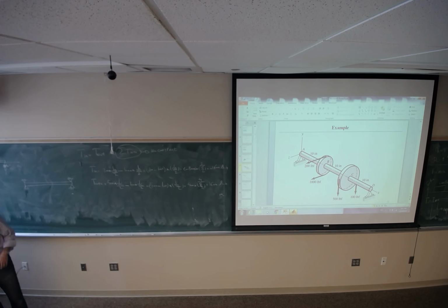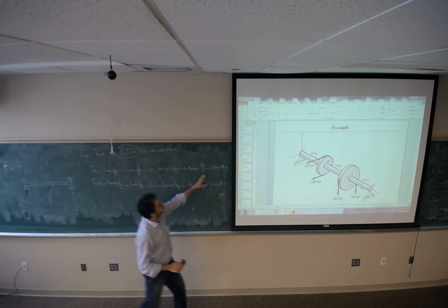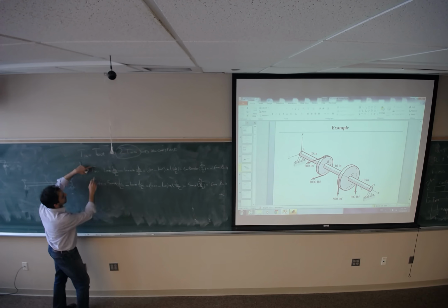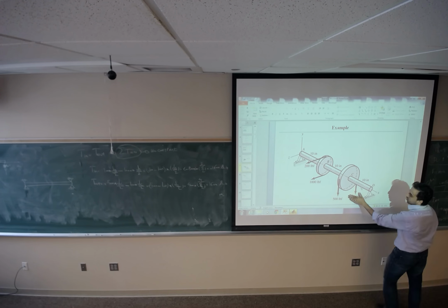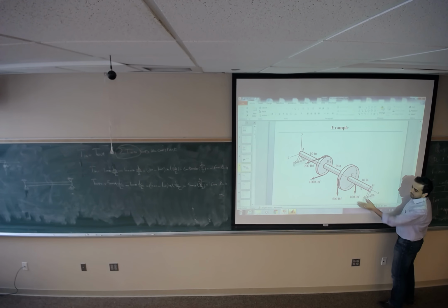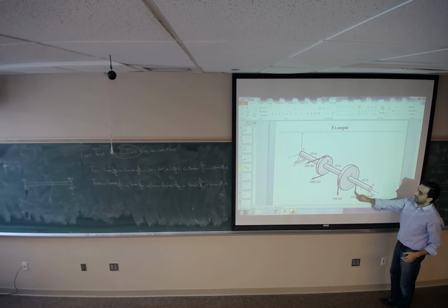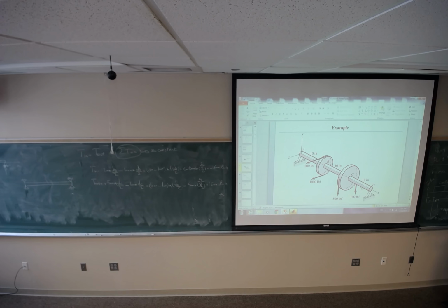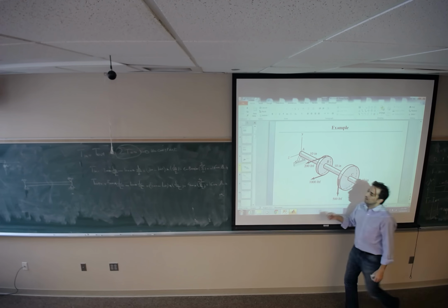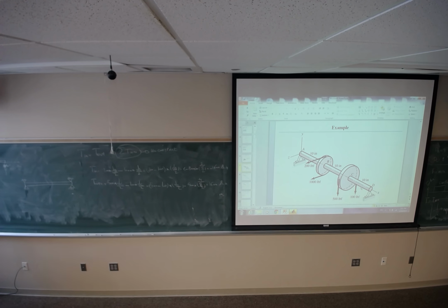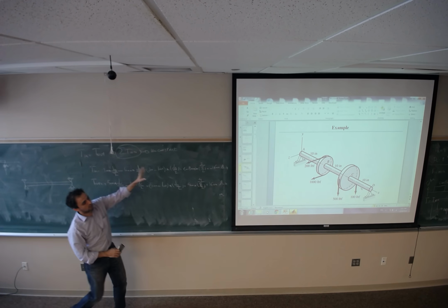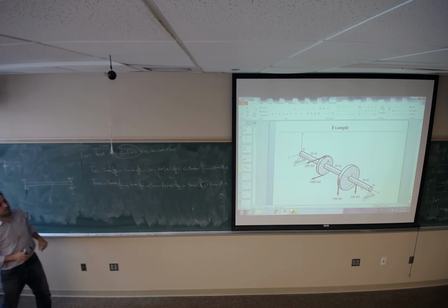As you see, the input torque plus output torque gives me 0. So I could remove this 100 and ask you what should be the tension at this side of the belts. You could calculate it, or I can remove any of those tensile forces on the belts. By setting up this equation, you can solve for that. But here I just showed you that it should be valid.